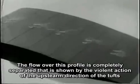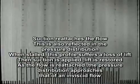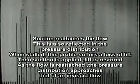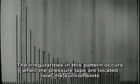The flow over this profile is completely separated, as shown by the violent action and upstream direction of the tufts. Suction reattaches the flow. This is also reflected in the pressure distribution. When stalled, this profile suffers a loss of lift. As suction is applied, lift is restored. As the flow is reattached, the pressure distribution approaches that of an inviscid flow. The irregularities in this pattern occur where the pressure taps are located near the suction slots.